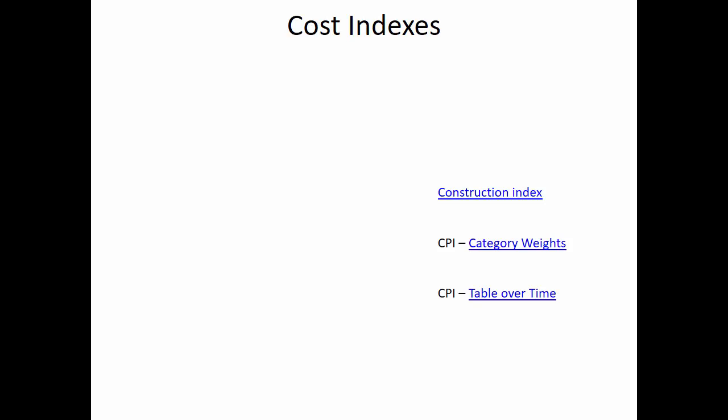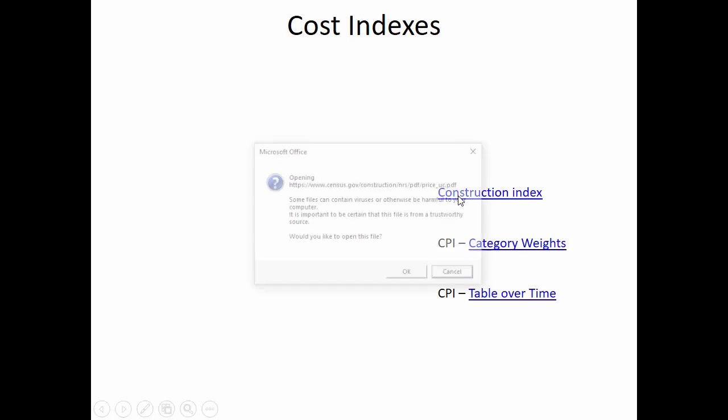So where do you get the data that goes into a unit method estimate? For example, here where it was saying $45.90 a ton for steel, or the machinery and tool costs. Well, one of the valuable sources of data, and how they change over time, can be cost indices. Let me show you an example of what a construction cost index looks like.